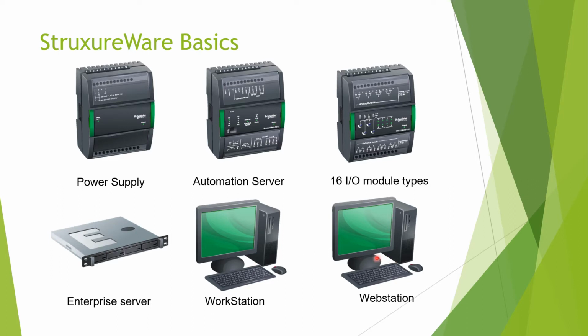WebStation uses a desktop web browser such as Firefox or Chrome to access and view EcoStruxure BMS servers. You can manage alarms and trends, change data set points, and override points with the proper access from WebStation. Any engineering functions, programming, and graphic changes, to name a few, must be done from Workstation.